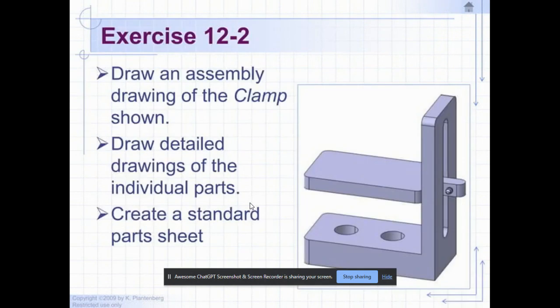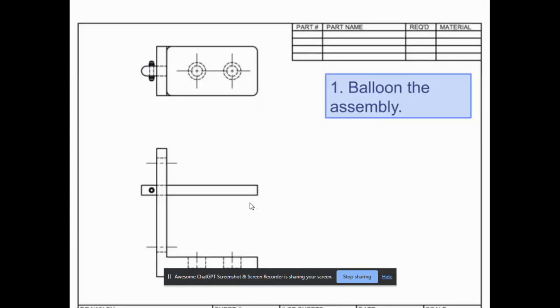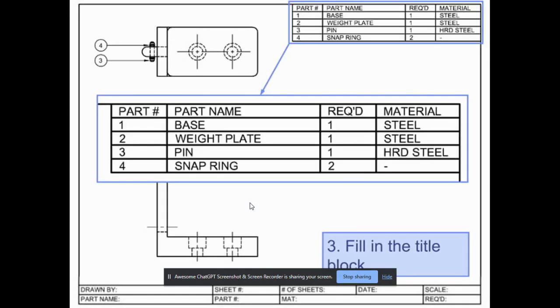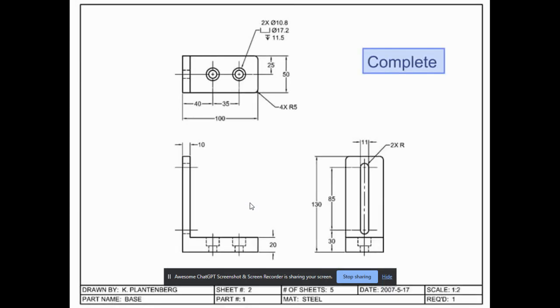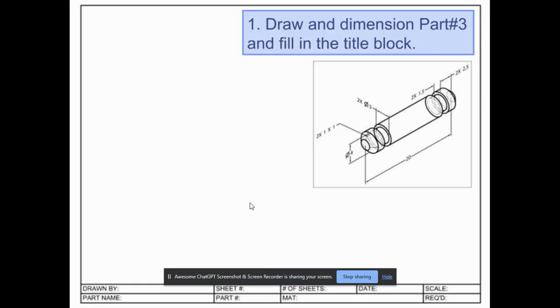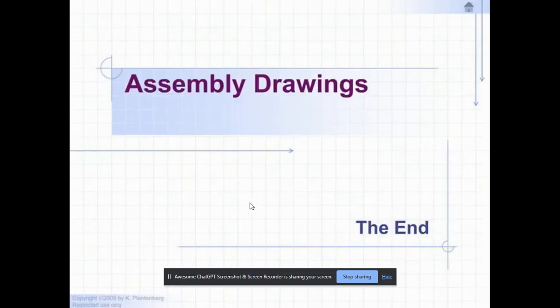So this is a sample of a working drawing, and like I said, the working drawing comprises the assembly, detail parts, everything coming together, ready for manufacturing. We have the drawings with the necessary views provided. We have the part list also provided here. Then we fill the part list with the names, and we have the balloons indicating the parts. And we also have the dimensions of that and all of that. I know we have an understanding of dimensioning, so there's no need to dimension it.